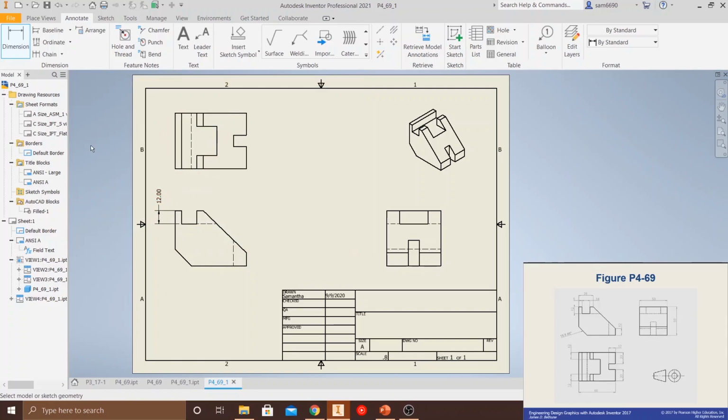If you click Escape so that you're no longer using the Dimension button, you can move how this is oriented. This area is a little too small for the 12 to fit in between, so you don't really have that option, but you can move it on either side, pull it away more, things like that. So let's go back into Dimension. Let's go across the big one first.